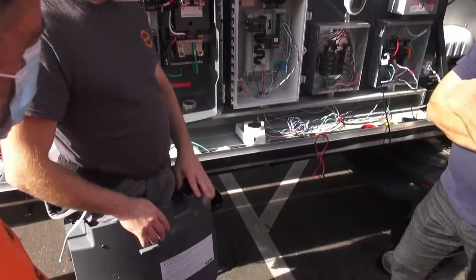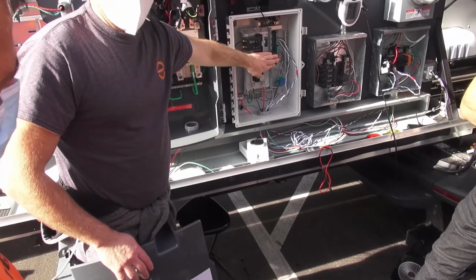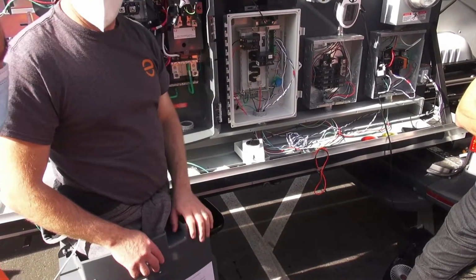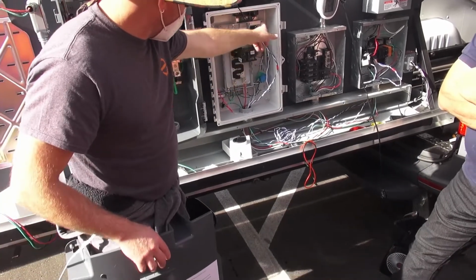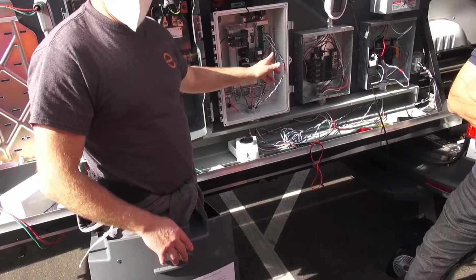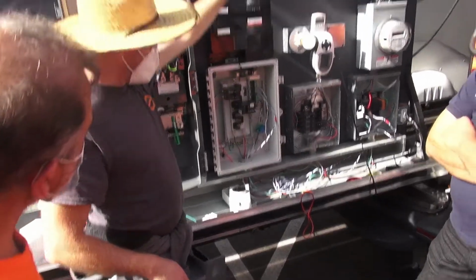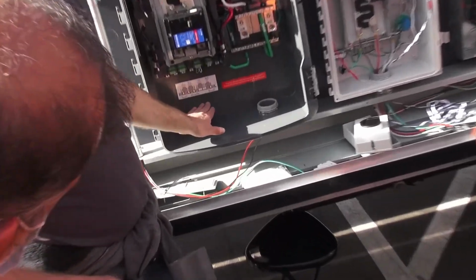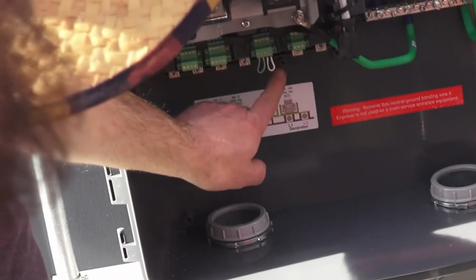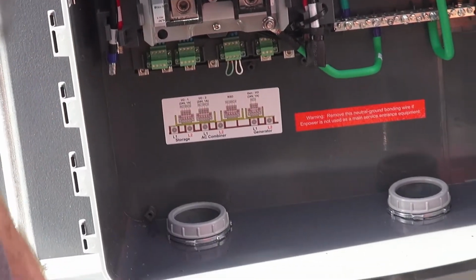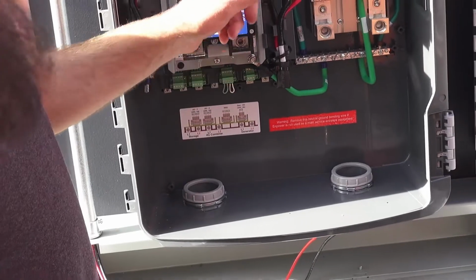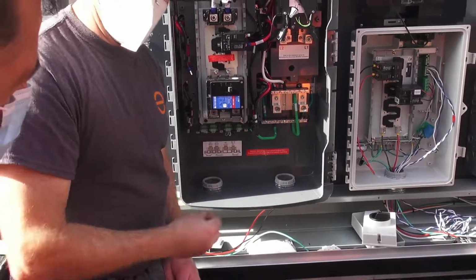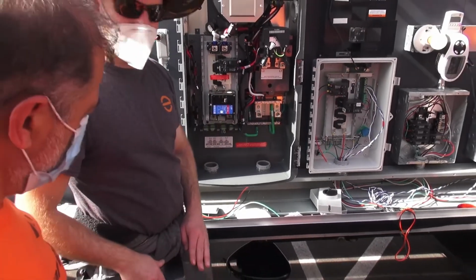With System Controller 2, you no longer have this in here. Do not put the Envoy power in this box. It has to come out. The reason is I want to keep this thing powered on as much as possible. If I leave it here with IQ8, there's a chance I'm going to turn it off, because if you remember from your training before, the PV circuit actually lands down here, right? And we can turn that circuit on and off with the electronics behind there. We want the Envoy to stay on, even if we turn on and off the PV circuits.